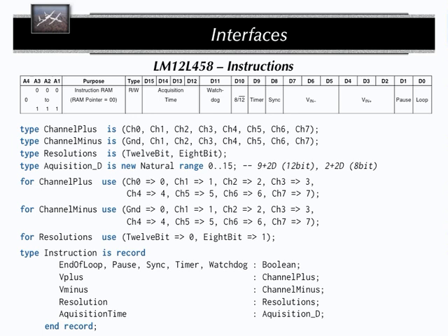So a linear enumeration type is not cutting it. You need to explicitly set these values to exactly the bit patterns which you want to trigger with that. This is what we do here. We say that the values for channel are supposed to be that. The values for the resolution, 0 means 12-bit, 1 means 8-bit. And then I can define a record out of all of these elements.